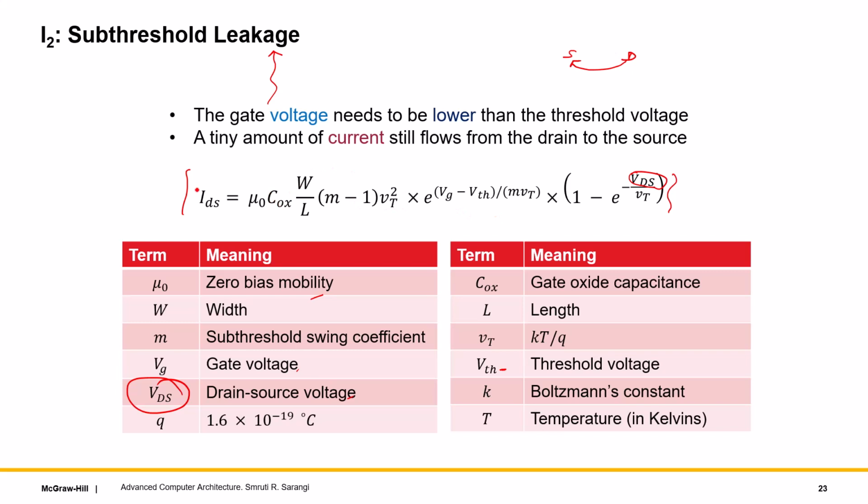So the leakage is a function of temperature. This is one thing that comes out. Previously it used to be an exponential function, but now it's not exponential, it's somewhere between linear and quadratic, mostly piecewise linear. So the leakage current is undoubtedly a function of the temperature. As you increase the temperature, the leakage current increases. This is the first takeaway point, which is a major point, that as you increase the temperature, the leakage current increases. This comes out from this equation.